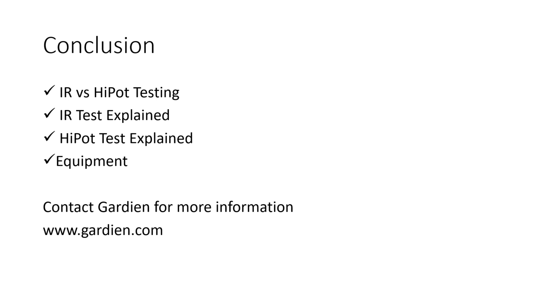So just remember that, and always pay attention to your procurement docs or the fab drawings, because they may call out a special specification such as the TM650 condition A or B, or they may have a specific requirement for voltage, whether AC/DC or whether it's a longer ramp time and a longer dwell time. So always be making sure that you get that information correctly to your service bureau or to us, to any of our service centers, so that we can get the test done correctly and have proper information for you on the certificate of compliance.